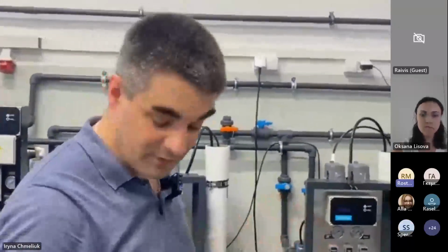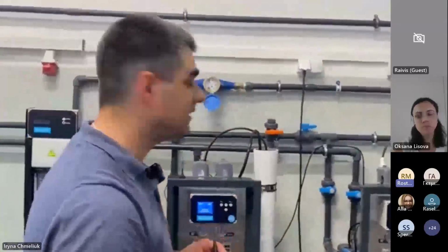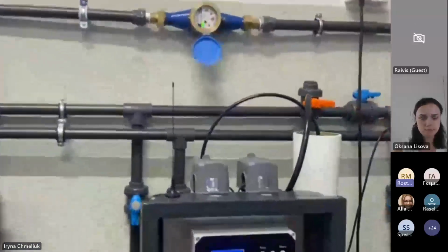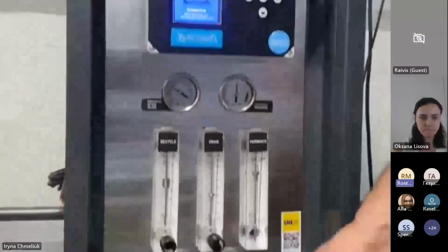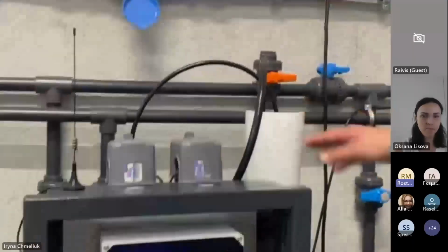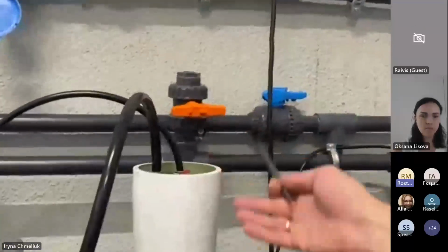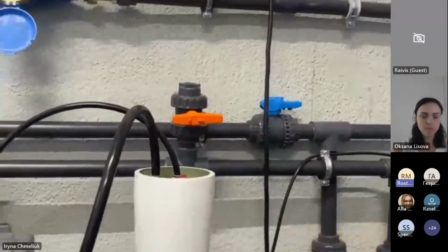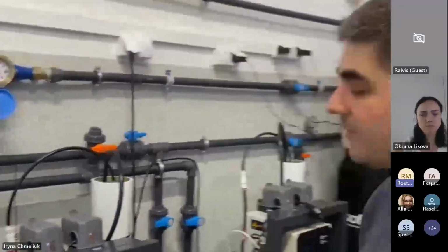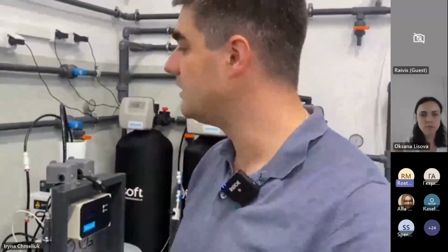And then if the water is clear and the tests are okay, you go to the reverse osmosis unit, and then you have to install the sediment filter. These are very basic rules, but this is what has to be installed. And also the membrane element should be installed, so it is already here. In this particular unit, we use the FilmTech XLE4040 membrane element. So this is what has to be done.